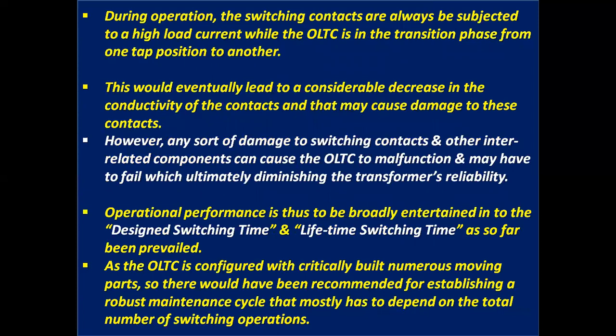During operation, the switching contacts are always subjected to a high load current while the OLTC is in the transition phase from one tap position to another. This eventually leads to a considerable decrease in the conductivity of the contacts, and that may cause damage to these contacts.